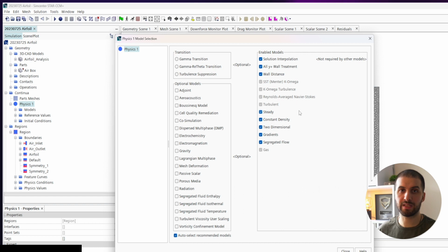If you might have seen some of the CFD podcasts on this channel, you might notice that almost all CFD experts always say, take your problem, simplify it to the most simple model that you could choose and increase the complexity step by step. Then if you increase the complexity by a little bit and tweak one more parameter, but the outcome is garbage, you can debug it very easily, saying this specific tuning of my model actually caused the simulation output to be garbage. So I can go one step back and rethink the parameter that I've tweaked. Okay.